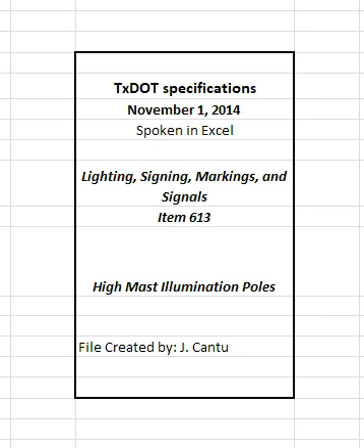Repair galvanized surfaces damaged in assembly, transit, or installation, or for steel parts or members welded after galvanizing, in accordance with Section 445.3.5, repairs. Provide riprap around pole foundations in accordance with Item 432, riprap, and the details shown on the plans.